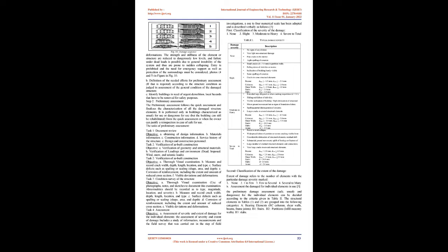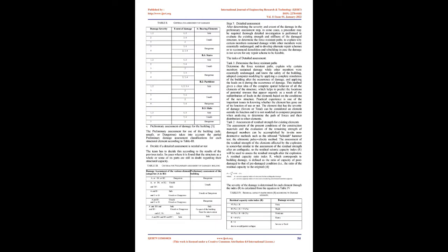Task 1, Document Review. Objective: A. Obtaining of design information. B. Materials information. C. Construction information. D. Service history of the structure. E. Design and construction personnel. Task 2, Verification of as-built construction. Objective: A. Verification of geometry and structural materials. B. Verification of loadings and environment, dead, imposed, wind, snow, and seismic loads.